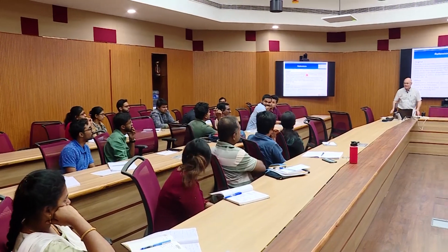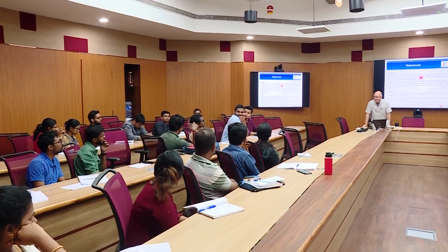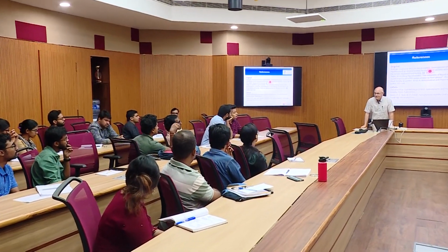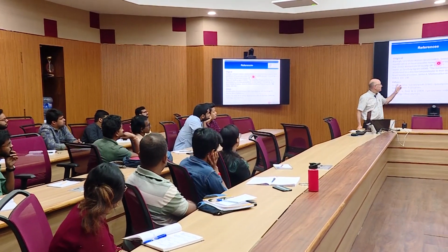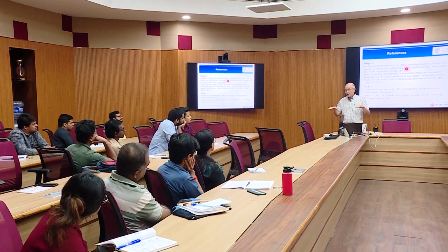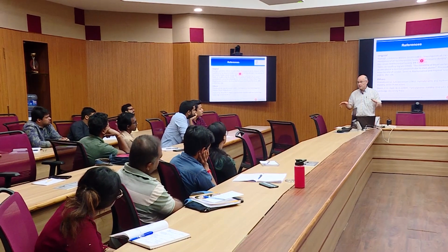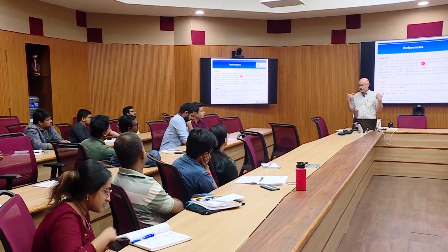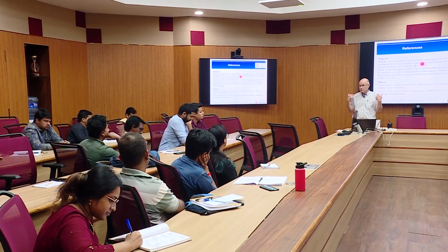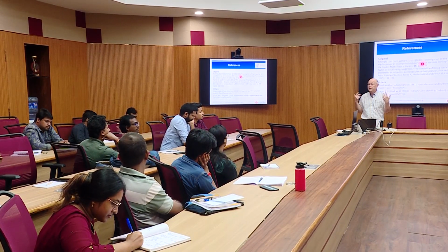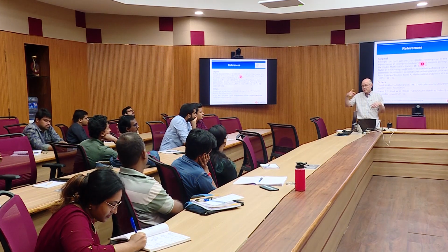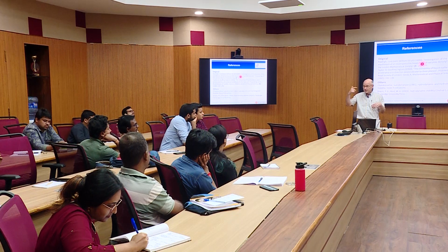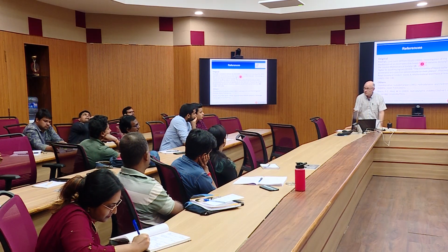If you impose any boundary condition, then how will the dispersion be? So here, there is no boundary condition on the flow. No, here we still have the boundary conditions. We have the kinematic boundary condition, and we have the Laplace boundary condition. We still have both in developing that dispersion relation for the Kelvin-Helmholtz, and that's also valid for the Rayleigh-Taylor. Those were the two conditions, one kinematic and one Laplace. Those were the boundary conditions.